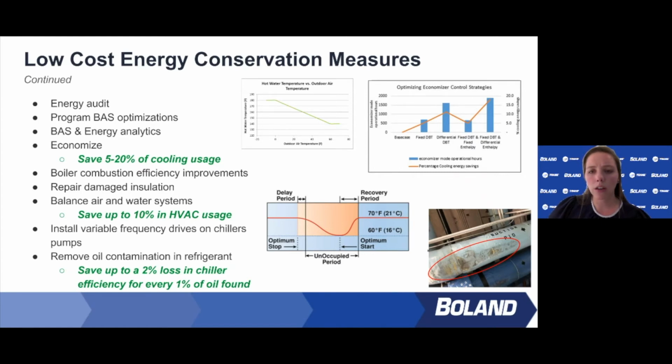And then also looking at an audit, you might know your chiller's old, but there might be more to your chiller plant. You could look at how the equipment's running, your set points, your sequencing, but then also tie in fenestration or insulation. So I like an energy audit to help you find a list of ECMs that you can take action on.